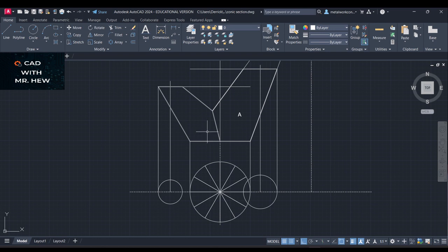to the two oblique circular cones, okay? All right, now the next step, what we're gonna do now, we're gonna draw lines, the intersection of these lines to the baseline, which is this line. All right, good. So we're gonna go line there to there, line from there to there.